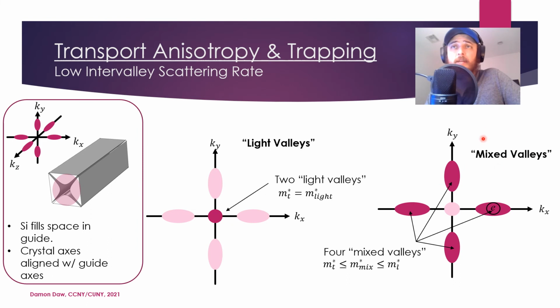The other four valleys are the mixed valleys, because depending on where the carrier is in the trap, essentially on what the angle between the electric field and the carrier valley is, they'll respond with any intermediate effective mass anywhere between the transverse and the longitudinal effective mass. This might happen, for example, in diamond. If you go to liquid nitrogen temperature, the intervalley scattering rate gets very low, but there's still enough acoustic phonons creating drag that you can still treat the particle like a Brownian particle, apply this framework we've developed, and still analyze the dynamics of the trapping or guiding.